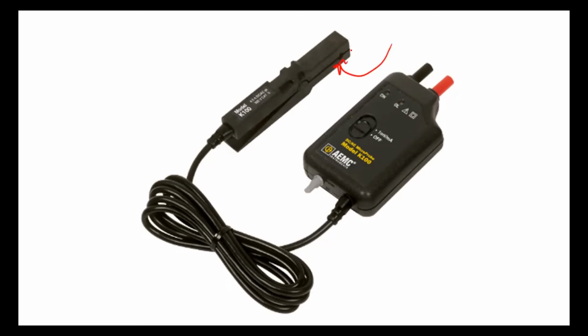Basically, clamp the probe around the wire. It won't take a very big wire either, I should mention that, but you simply clamp this around the wire that you want to measure, hook this up to your scope or your voltmeter or whatever you want to use. And it does have a scaling of 1 millivolt per milliamp. So we're just going to hook it up on the signal wire and see what we can see for amperage.